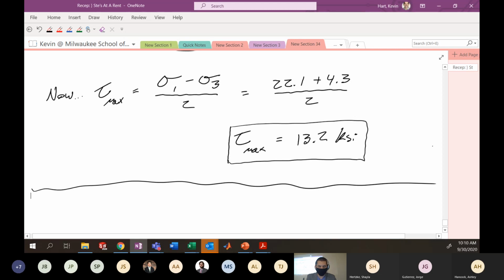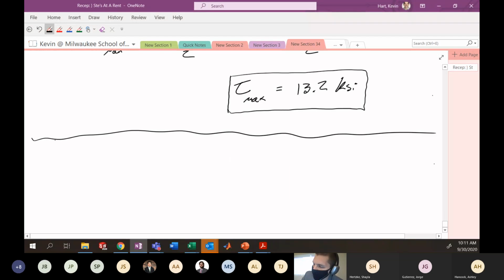All right, so new set of notes. And that's failure criteria. So, we really have to hammer home on principal stresses before we talk about failure criteria, because failure criteria for materials are dependent on your ability to calculate principal stresses. Pretty much every failure criteria that you see for materials will use principal stresses as a basis. So we have to be very comfortable and familiar with principal stress to do that. So here we go with static failure criteria.